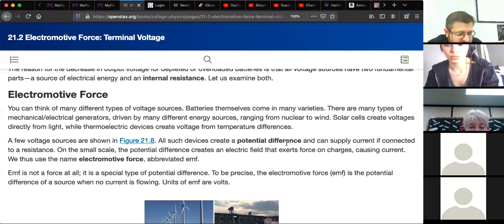Some cars actually have a voltmeter connected to the battery on the dashboard, so you can actually see the voltage in your battery. If you've ever watched that, you can see that it changes while you're driving. While you're just driving along the highway, it's usually at a pretty high voltage. But when you're starting the car, the voltage usually drops pretty dramatically. And if you're just sitting idling or stopping and going a lot, it usually oscillates a little bit.